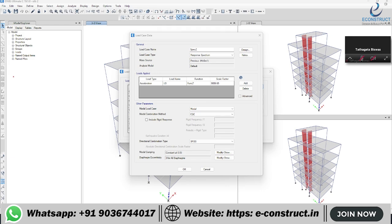You don't need to check anything for spec Z. What you need to do is check the base shear, just once. No need to check anything else. After that, whenever the spec X and spec Y base shear is finalized and you are opting for design, before that there will be a final scale factor for these two. The maximum one among these two you will take and put it here, replacing the existing value.